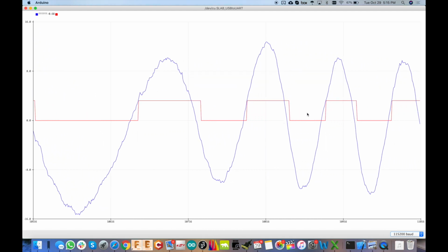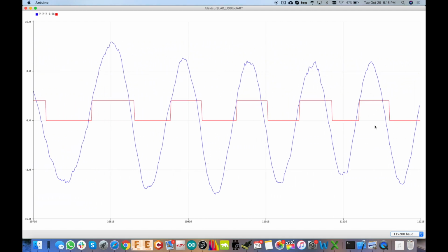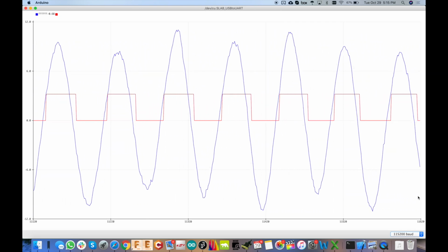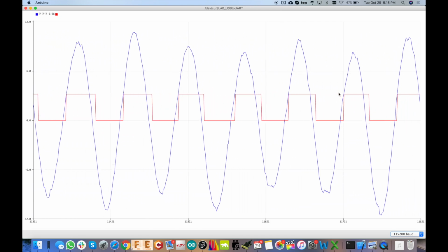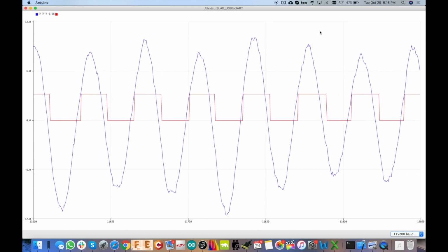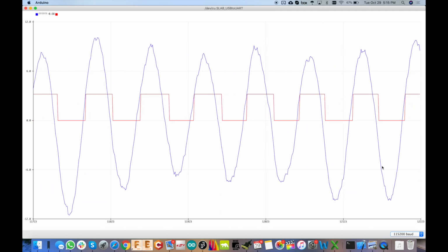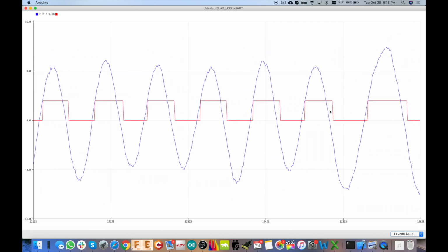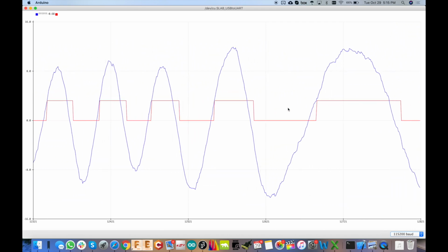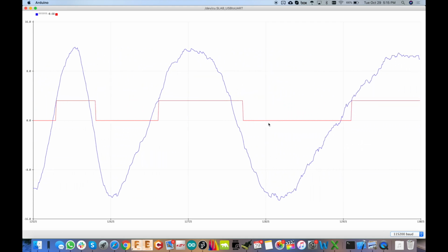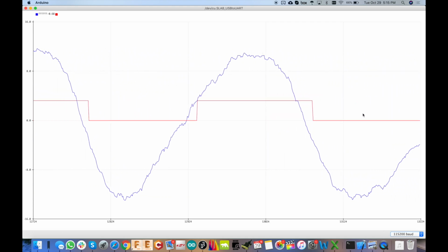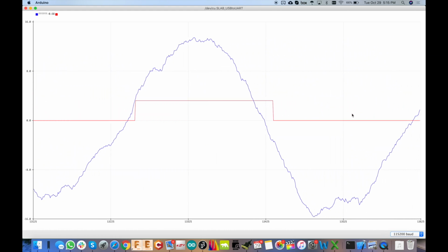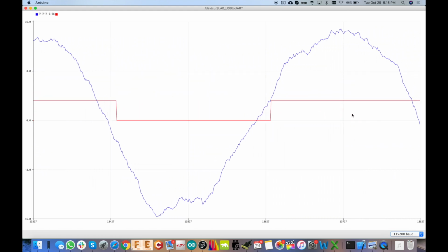And there you have it. So now you see we're getting a waveform, and it's very sinusoidal as that magnetic wheel is rotating within the meter. Now, a couple things to point out here is notice that the amplitude changes and the frequency of this waveform changes as the water flow changes. And there you go. So as the toilet there is finishing off, the amplitude is starting to decrease. Obviously, the frequency is decreasing.